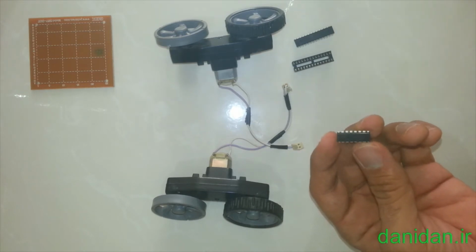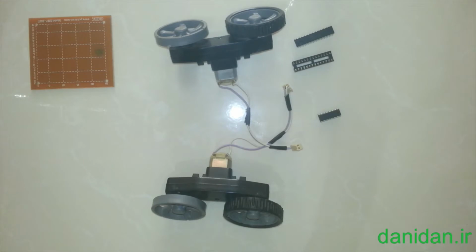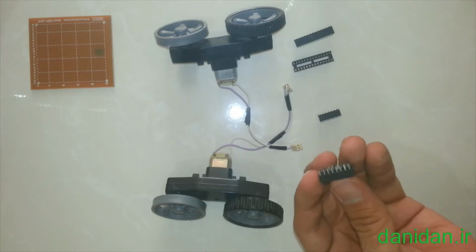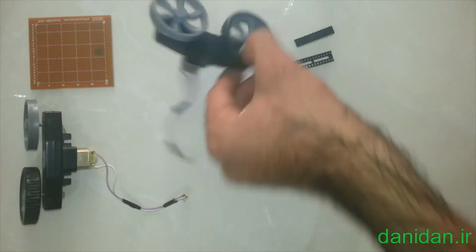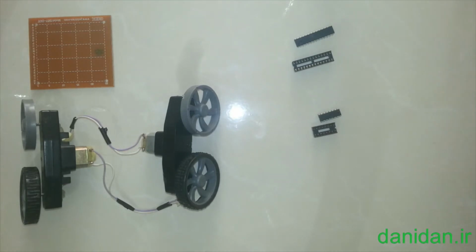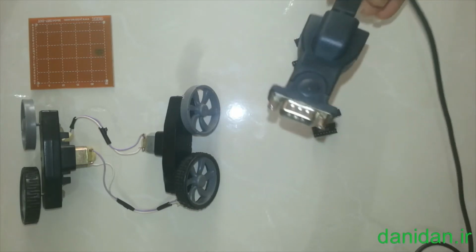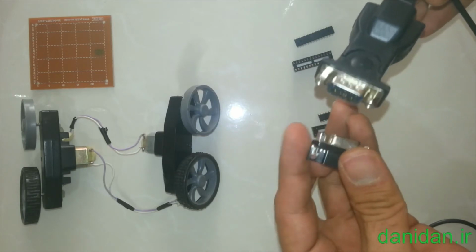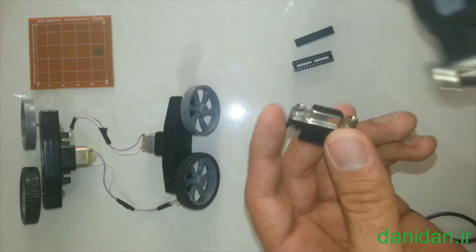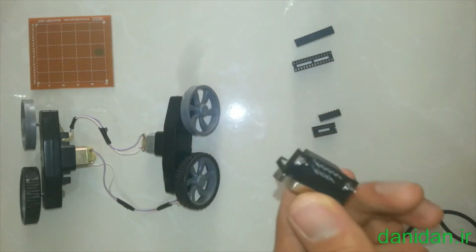To run our motor, we need to send the data from the microcontroller to the motor. We need a driver, and at this time I use the L298 IC. This IC helps you to drive your motor. So also we need a circuit for this IC. As I said before, to send the data from the mobile phone, we need a USB to serial cable, and also we need a connector to connect our USB serial to the robot. So I bought a 90-degree pin socket for this purpose.